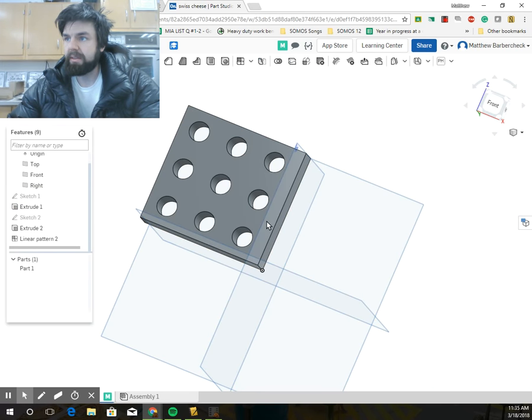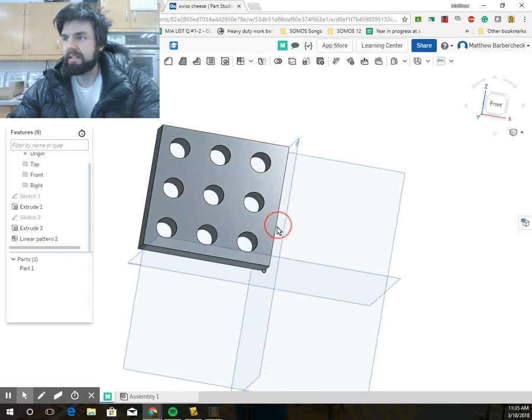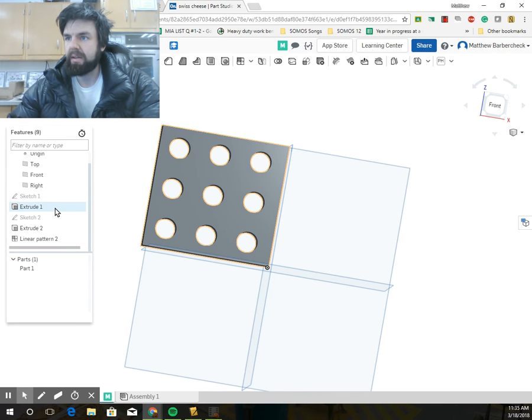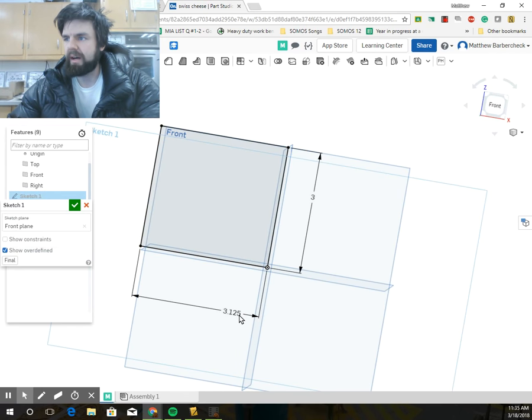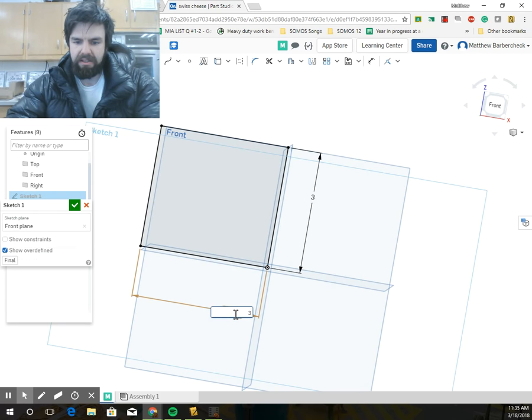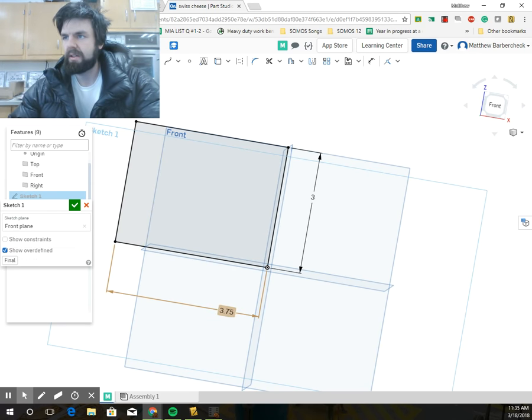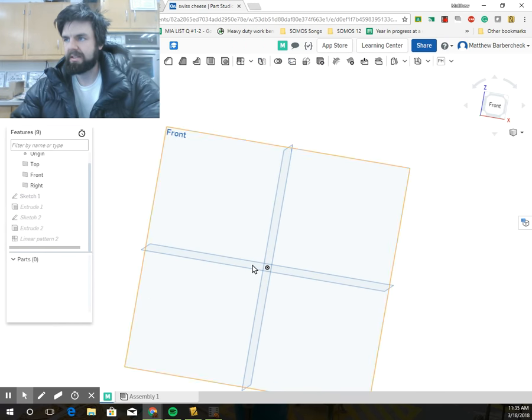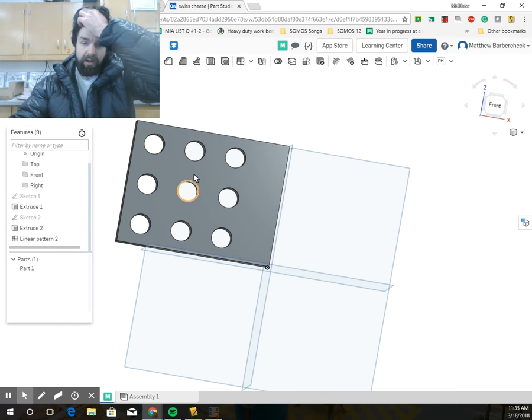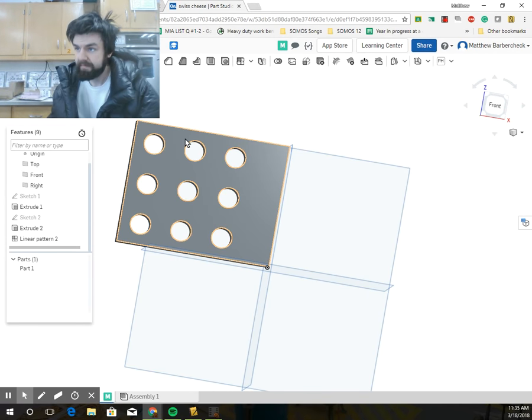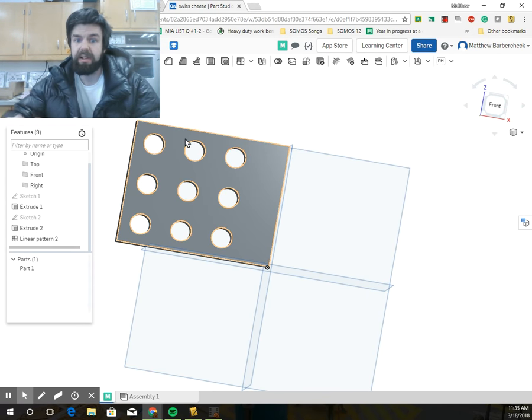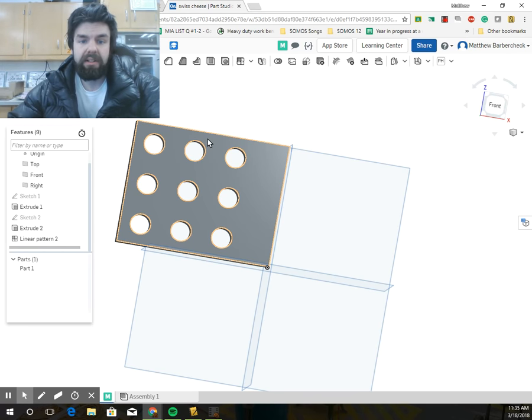All right, what that does is, see how we're not symmetrical even anymore. In fact, I'm going to go in and make it a little more obvious so that we can see it. I'm going to go ahead and make it 3/4 of an inch and get a better representation of what we're talking about. Okay, the holes are no longer symmetrical. And so even in that 1/8 of an inch situation, the holes would no longer be symmetrical. Whatever this part's used for, you probably want to be able to maintain its intent, maintain what it's supposed to do, with those holes out of alignment.